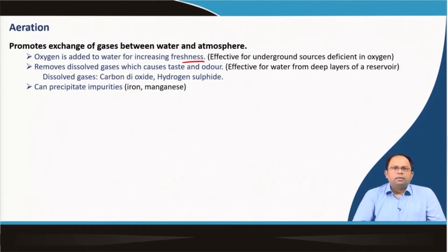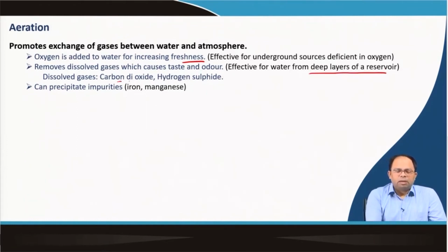The exchange of gases also involves removal of dissolved gases, which cause taste and odor. This is again effective for water from deep layers of a reservoir, which usually have dissolved gases such as carbon dioxide and hydrogen sulfide. Sometimes aeration can also precipitate impurities such as iron and manganese by formation of certain oxides.